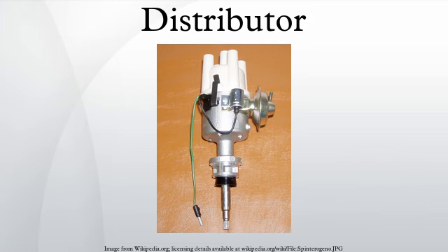Description: a distributor consists of a rotating arm or rotor inside the distributor cap, on top of the distributor shaft, but insulated from it in the body of the vehicle. The distributor shaft is driven by a gear on the camshaft on most overhead valve engines, and attached directly to a camshaft on most overhead cam engines. The metal part of the rotor contacts the high-voltage cable from the ignition coil via a spring-loaded carbon brush on the underside of the distributor cap.